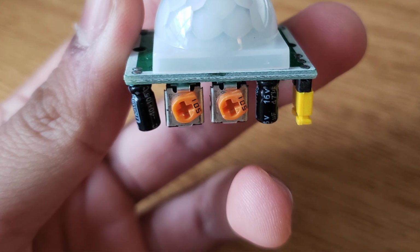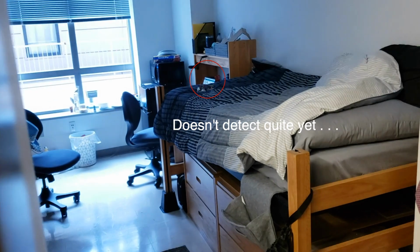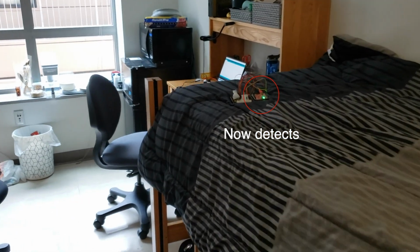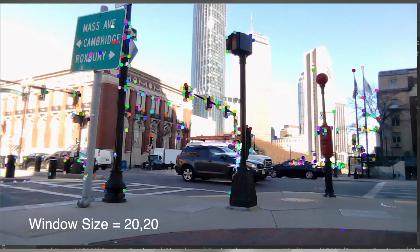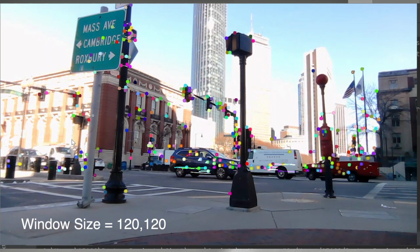Another important takeaway we found was that the abilities of motion detectors are not fixed. Tweaking parameters is an easy process, but it does result in trade-offs. We can tweak infrared sensors to avoid picking up noise, and we can play with parameters in the difference of frames techniques to determine the amount of subtlety we are willing to pick up on. We can tweak the window size in the Lucas-Kanade algorithm to either precisely approximate motion vectors or track larger changes with larger windows.